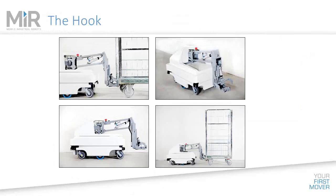There's also some top lift systems that are available for this, but the hook is one of the most popular options. So this hook has 3 different actuators on it. It's got a linear actuator here that's powered by the 24 volts off of the robot, and that allows this whole hook assembly to go up and down. So when it's getting ready to pick up a particular cart, it will lower its hook down to the area that you've pre-programmed for it to allow it to glide underneath the cart. Then it will raise that back up to the point where it'll be able to clamp onto the cart itself.